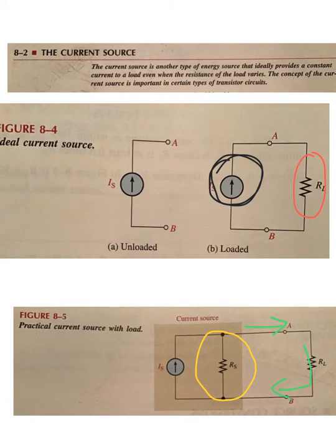You'll remember back here in Figure A that I talked about the resistor that sits between there is essentially large, like air. The resistance of air is infinite. So the ideal current source has infinite resistance, while the practical current source has huge resistance built into it. Okay? Are you with me so far? Fantastic.